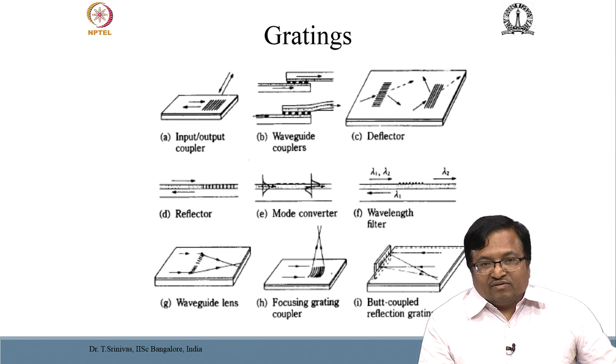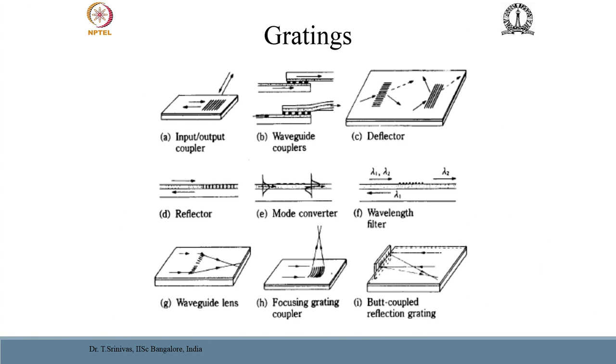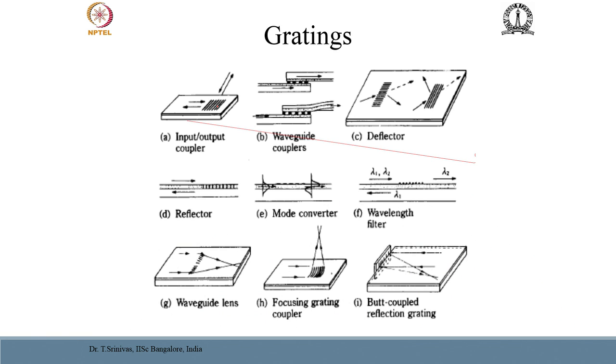So, gratings have many functions in many applications in optics and integrated optics. I am showing you some applications. The gratings can be used as an input output coupler. This is one of the important applications presently. One of the important problems I can mention in integrated optics is coupling light from input optical fibers onto the chip, and gratings do a very good job in this connection.